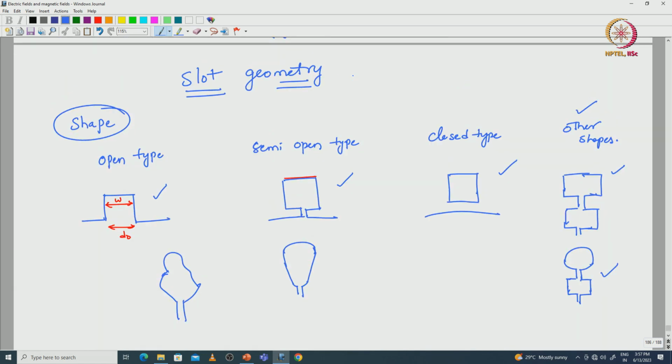We can see here, in order to insert the windings into the slot, assume that here one conductor is there of thickness 10 mm. Here also some conductor is there, here also conductor is there. If we want to insert this conductor into the slot, in open slot it will be easy, in semi open type of slot slightly complex as compared to the open type of slot.